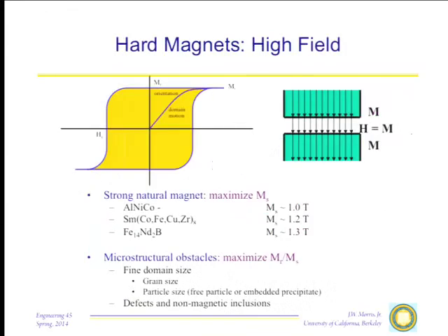Well, there really are two kinds of magnets that we identify. And we identify them on the basis of this hysteresis loop and the remnant magnetization. The first and the simplest, most familiar to you probably, are what we call the hard magnets. A hard magnet is a magnet that will retain a magnetic field. If you want to make magnets to use in children's toys or to lift scrap metal in a junkyard or to act as memory elements in memory devices, you want things that you put the magnetic field on and it will stay there. It's not going to go away.